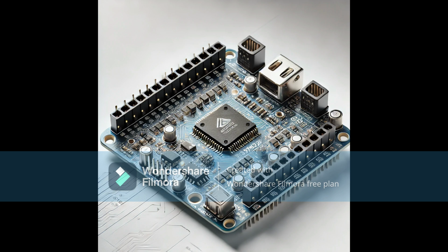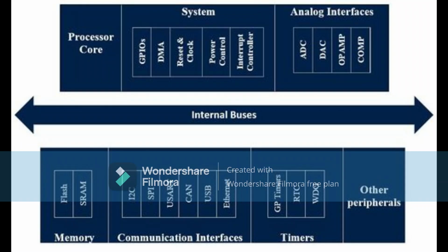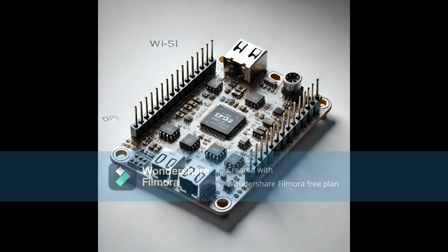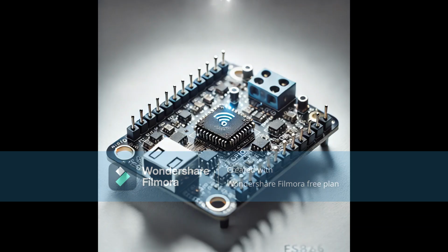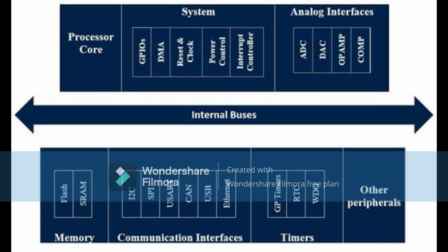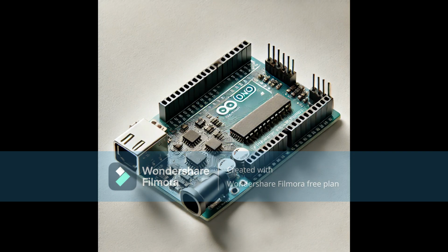Point 2, microcontroller architecture. A typical microcontroller includes a processor, memory and input-output (I/O) peripherals on a single chip. Its components may be extended to include digital I/O, analog I/O, timers, communication interfaces, and a watchdog, a timer that is responsible for the detection of timed-out or locked instructions. A processor is a little chip present in the device that has the role of arranging the instructions and ordering the outputs. The manufacturer defines the integrated peripherals and the hardware capabilities. This is the basic layout of a microcontroller.